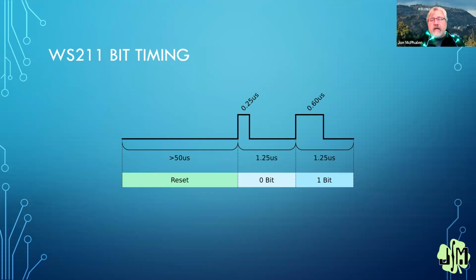So my buddy Rick, because 3.3 volts is a little bit on the ragged edge of the input voltage requirement for some of the pixels, he'll just put a pixel on his board and use it as a buffer. So pixel 0 is on his board and pixel 1 is the first thing that's in the object.